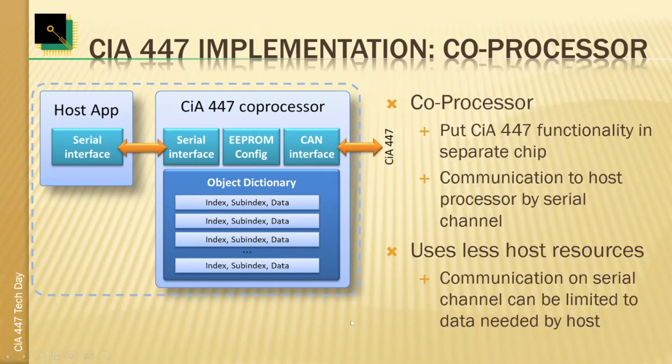So the coprocessor solution is really a nice option we see used specifically for devices that, as I said, have graphical user interfaces and complex, non-real-time operating systems running. And of course, the resources now required on the host side are less, because literally this is also a filter towards the host, and it doesn't bother the host with things that it doesn't need to deal with.